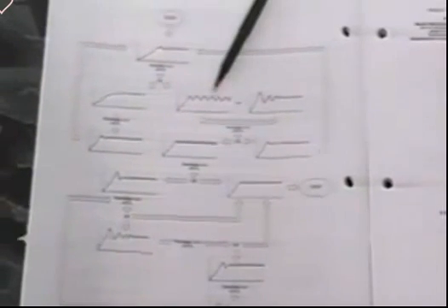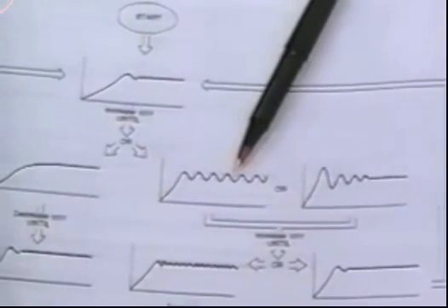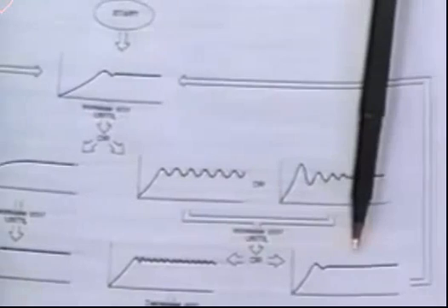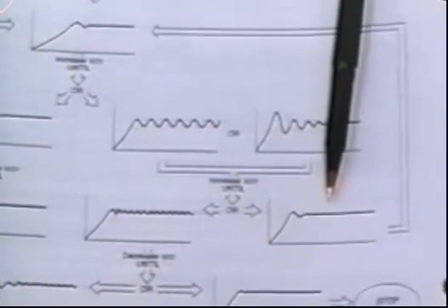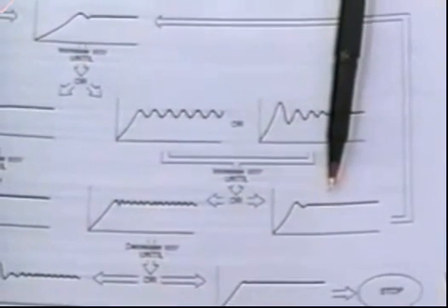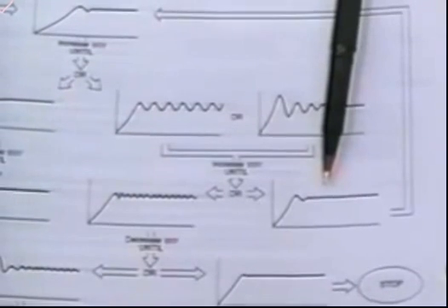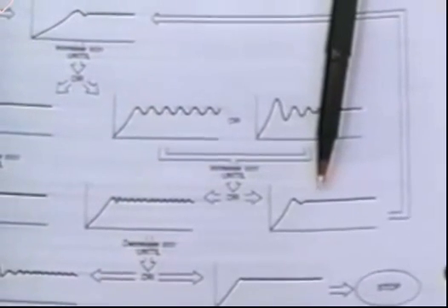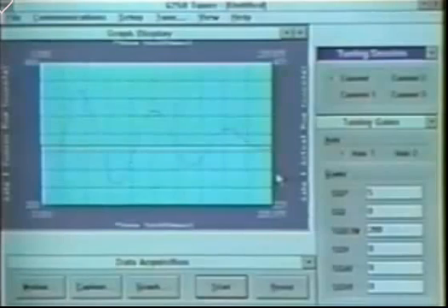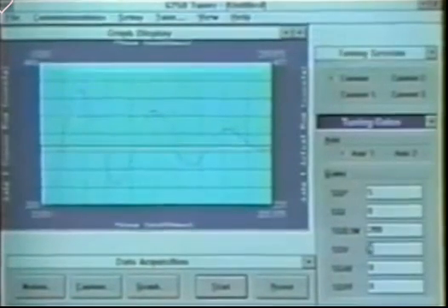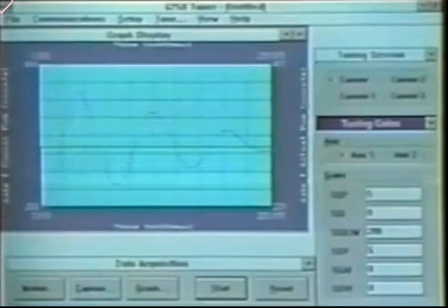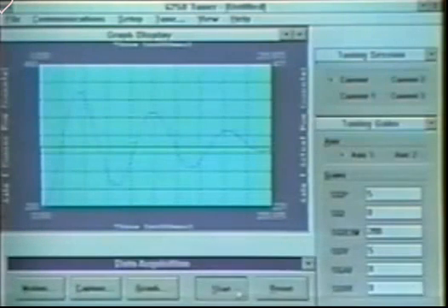As seen in the graph display, this is an oscillating underdamped case. In our flowchart, that puts us right here. Our flowchart tells us to increase the velocity gain until we achieve one of these graph profiles. The velocity gain increase dampens out oscillations. Following the advice from our flowchart, we will now increase the velocity gain from 0 to 5 and start the tuning procedure again.